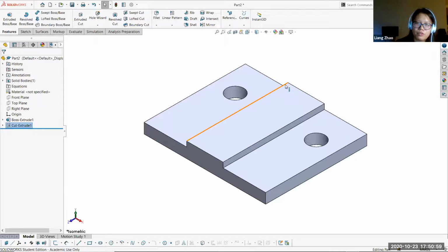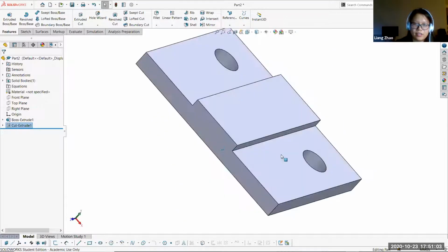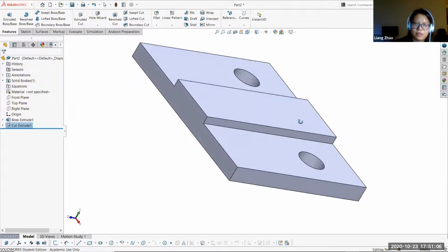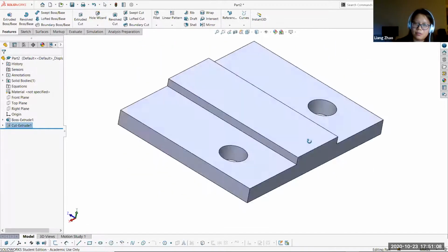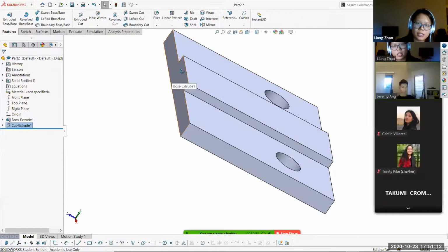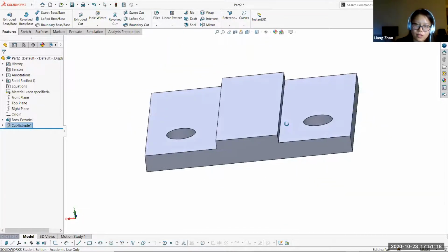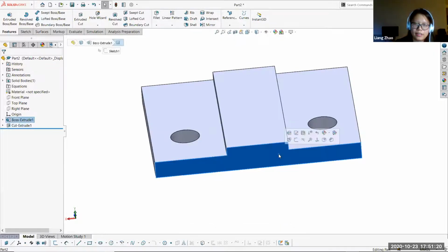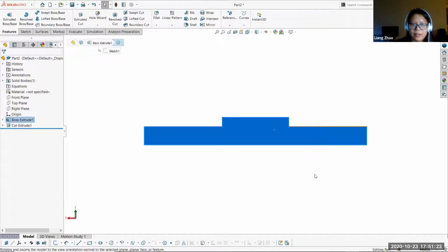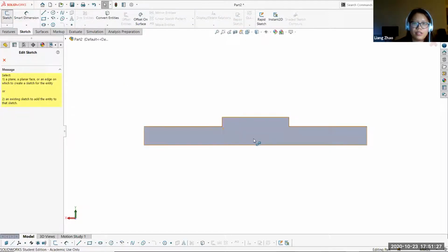So that means we want to draw on this face here instead of on this face for simplicity purposes, because otherwise we will have to use a reference object for the extrusion to come from this side. So I'll go ahead and click here again and use the normal to command again. And I'll start the sketch here